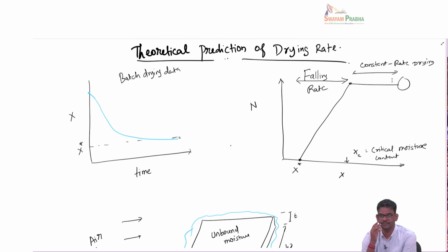That is one assumption. The other assumption is that this liquid is evaporating at Ts and going into the air stream, but the air is flowing at Tg. So this moisture has to be heated by sensible heat from Ts to Tg, and that would be Cp times (Tg minus Ts).